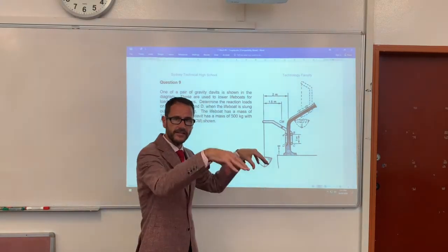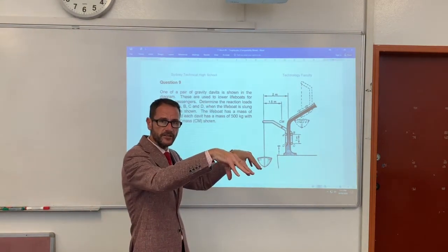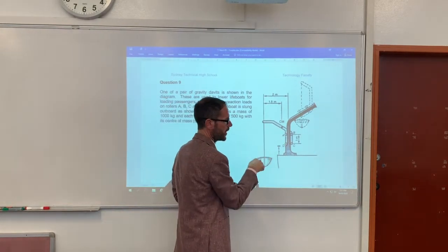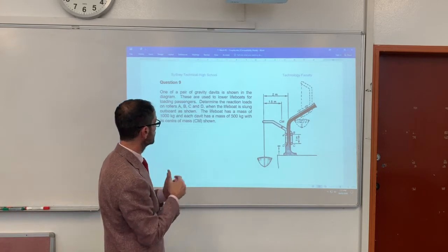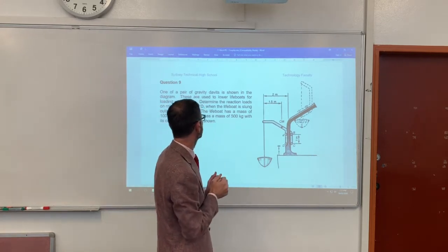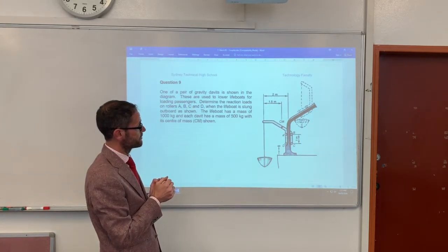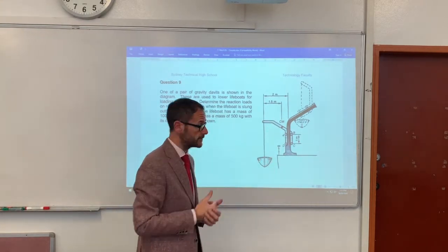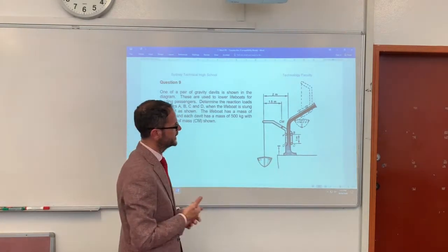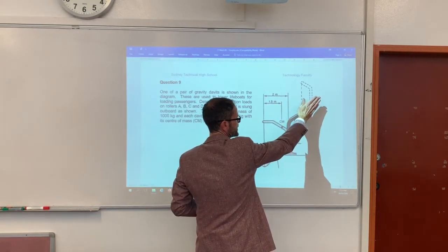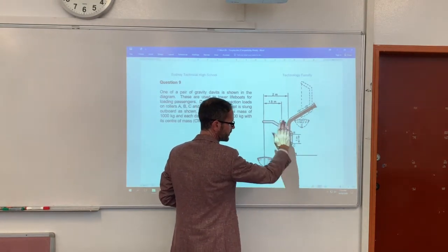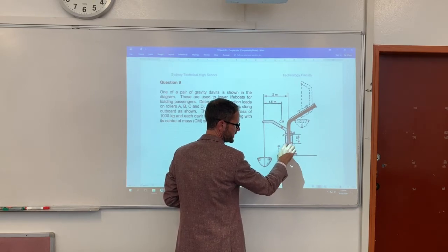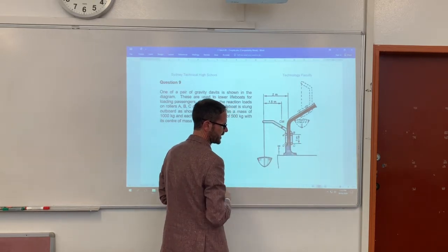So the boat is held at both ends by these davits, and we're only seeing one of them because they're behind each other. So the load of the lifeboat is shared between these davits. We've got one davit shown, and the other is immediately behind it so we can't see it. This is the parked position, it's now rolled down, and when it rolls down, these rollers sit on this little step here at D. That's what stops it going down any further.